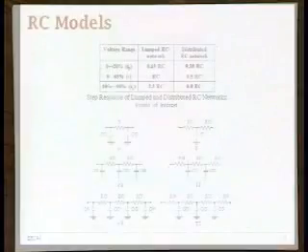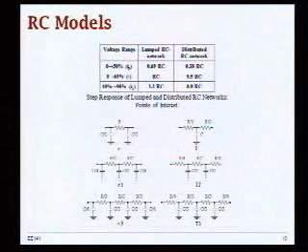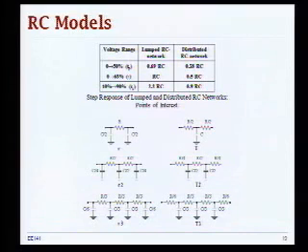So now let's go back to slides. And this is the type of RC models that you normally use in SPICE. Even simulation of the fully extracted RC, distributed RC model in SPICE can take a very long time because the way SPICE works is basically it inverts matrices. When you describe a system, you can basically describe it as a linear system with a certain matrix of R's and C's and so on.